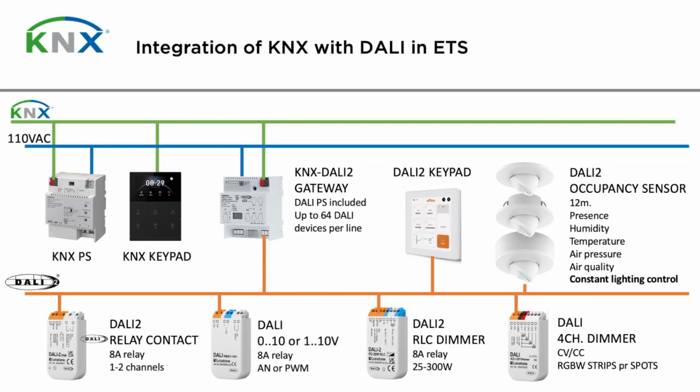DALI is not only to control the lighting fixture, but also to get feedback. This is very important in terms of maintenance. We can have the information of how many hours the light has been on, how many hours some group lights are on, or if there is a problem in the ECG or in the load. It's not just control like 0 to 10 volt controllers, but I also get feedback from the ECG.